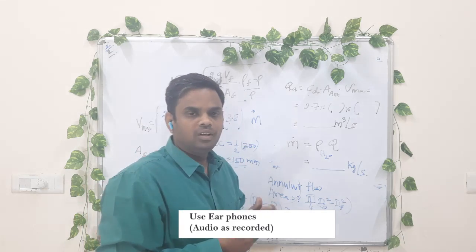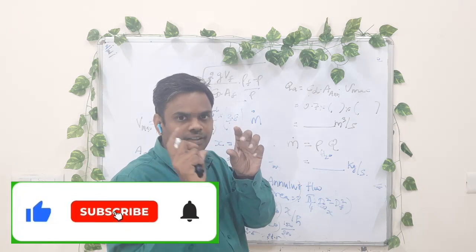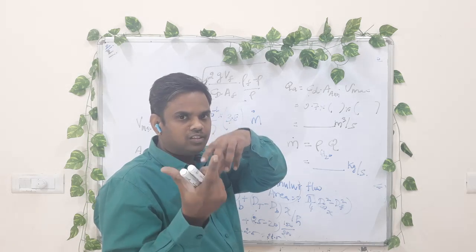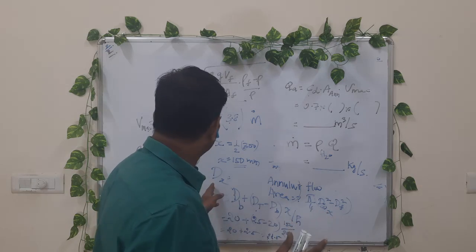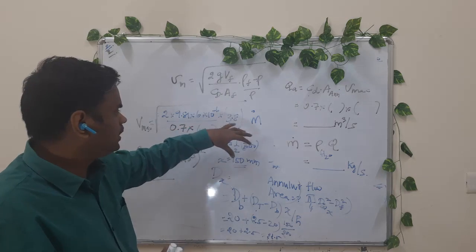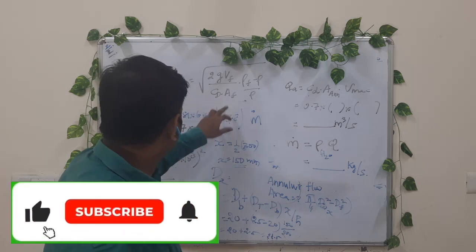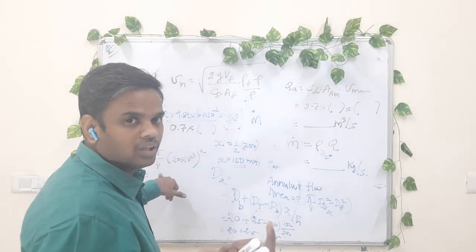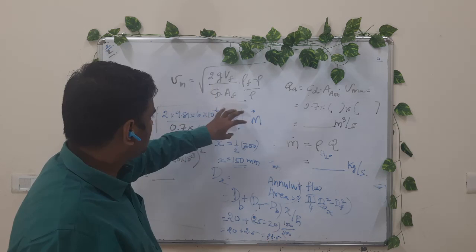22.5 mm. From that we calculated the annular flow area, the gap between the tube diameter of 22.5 and the float diameter of 20. Between that region, what is the flow that can take place? The cross-section area for that is determined. After that we find Vmax using the formula, because the density of the float is known and the density of the fluid is known. CD is taken, and the area of the float can be calculated by taking the bottom diameter of the rotameter and the diameter of the float. We get the AF value. Substituting it, we get Vmax.